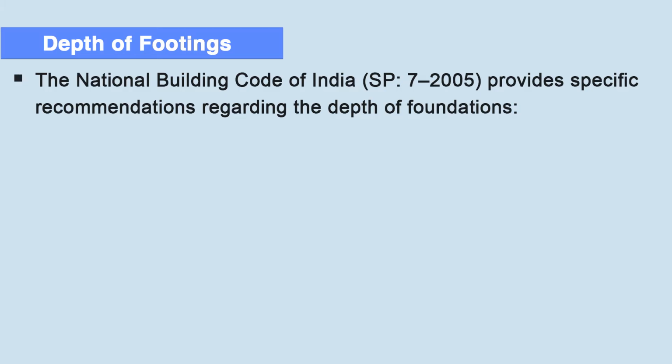The depth of the footing should also ensure that the rate or angle of load spread from a wall base to the outer edge of the ground bearing does not exceed permissible values. This consideration is crucial for maintaining the structural integrity of the footing. The National Building Code of India, that is SP 7:2005, provides specific recommendations regarding the depth of foundations.